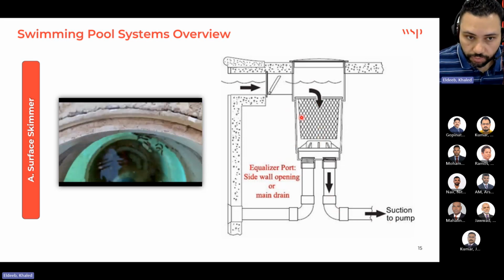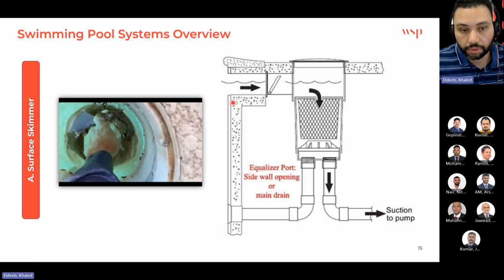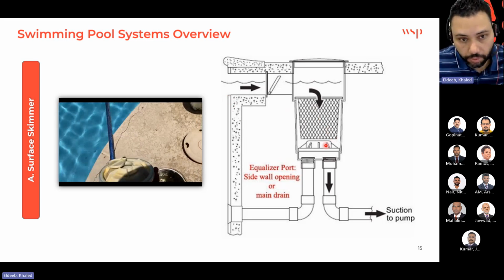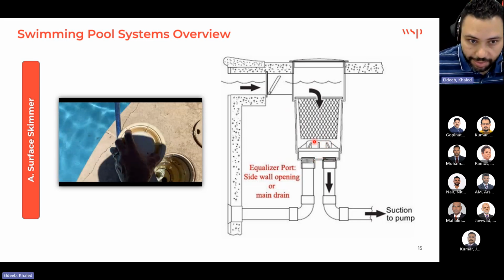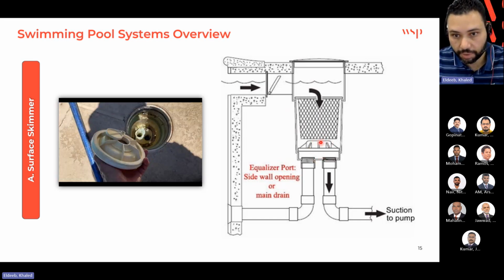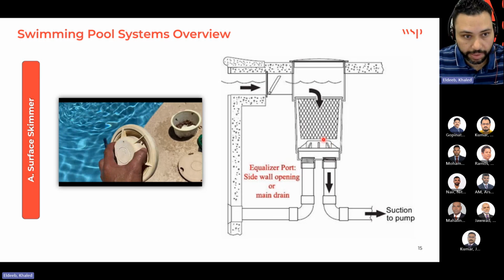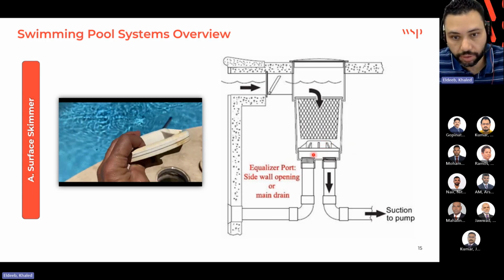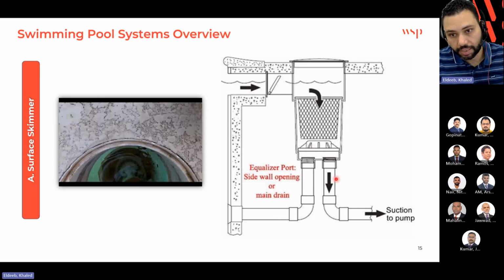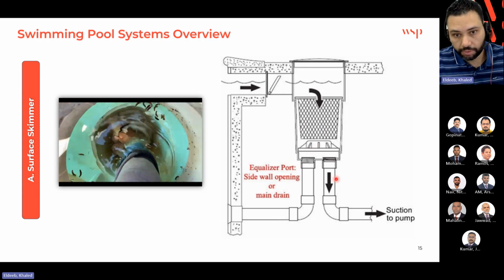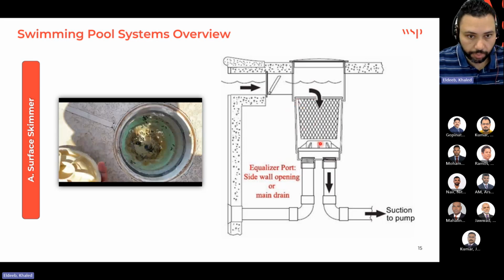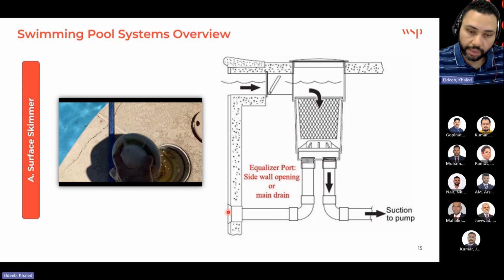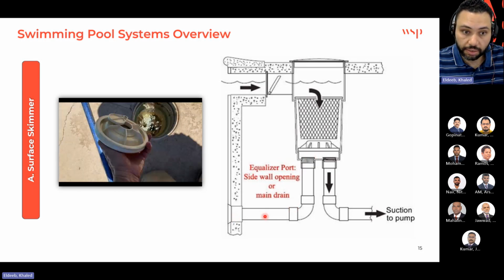In case, for example, the water level goes down, or debris like leaves or papers clogs this small piece, the skimmer diverter plate, the one that we see in the video, helps to ensure proper circulation and protect the pumps from running dry if the skimmer basket gets clogged, or if the water level drops below the skimmer opening. In this case, it will divert directly to take the suction from the pool.